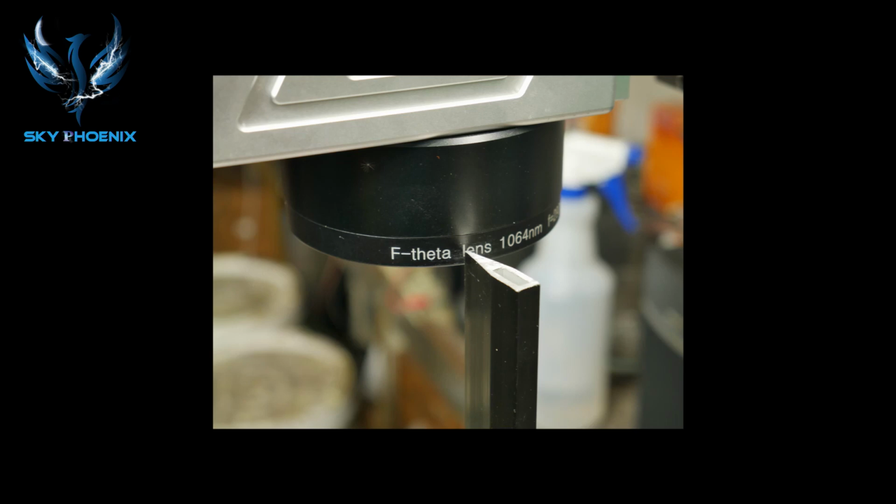And in this video, you'll hear the difference in the burning where I go past focal point, both too low and too high, and you kind of find the midpoint where it's burning the loudest and you can hear it's the most aggressive. That's your prime focus.